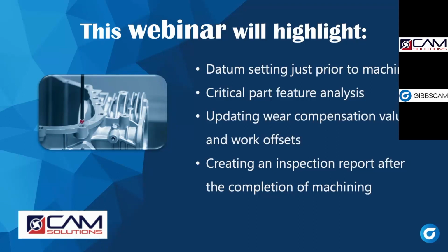This webinar will highlight datum setting just prior to machining, critical part feature analysis, updating wear compensation values and work offsets on the fly during the cycle, and creating an inspection report after the completion of machining.